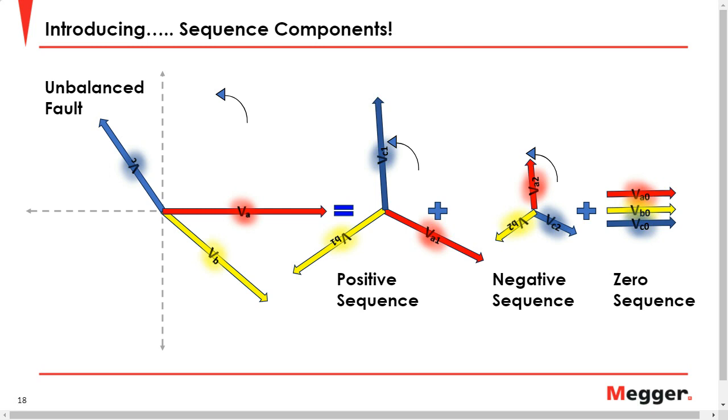And in particular for motors, the recommendation for the voltage imbalance is something below 5%. And I have also seen that something like that applies for the ratio of the 51Q, or negative sequence protection, to the positive sequence protection. Okay.